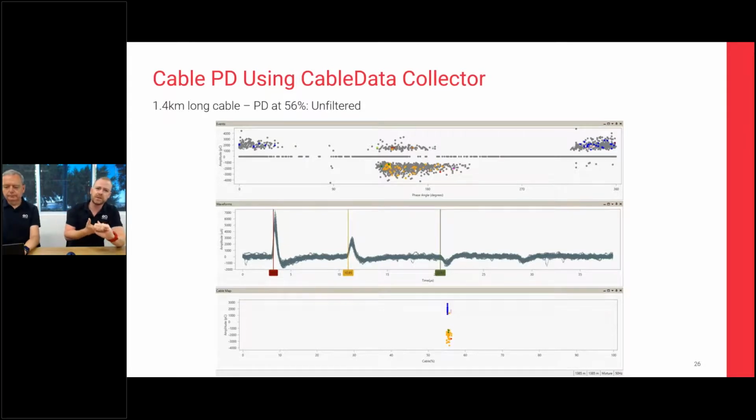There are two high pass filters that we apply to the data, which help us, A, detect if there's PD occurring, and B, get rid of noise. As I said earlier, usually there's a lot of electromagnetic noise on all our high voltage cables out there because your system's connected to everything and signals are bouncing off everything. So we use the filters to see through the noise so we can see PD. But also, the higher level filter that you apply, the less distance down the cable you can see. So we use that information to our advantage as well.